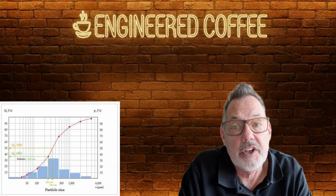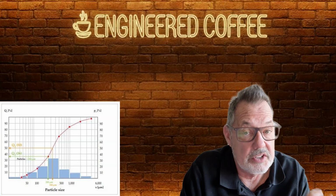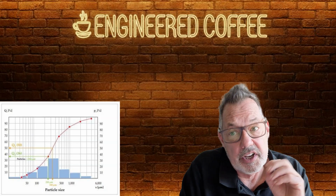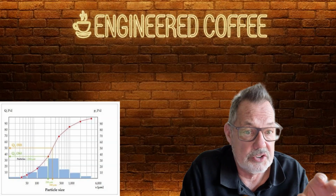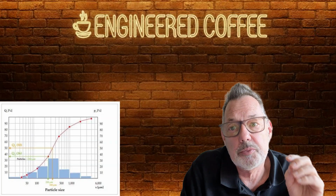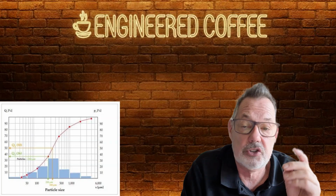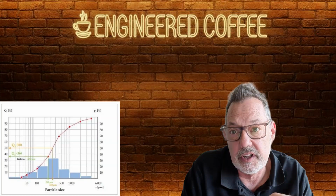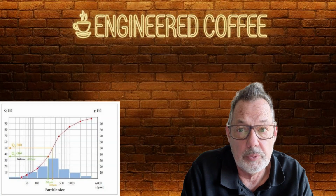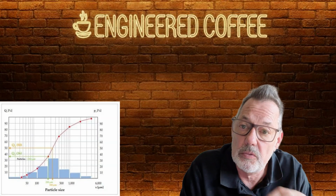So why we constantly monitor the PSD, particle size distribution. In our case, we use laser particle size analysis every 30 minutes because small shifts in the PSD can have huge effects on extraction time, pressure profile, crema formation. We're not just measuring for curiosity, we're measuring for control.